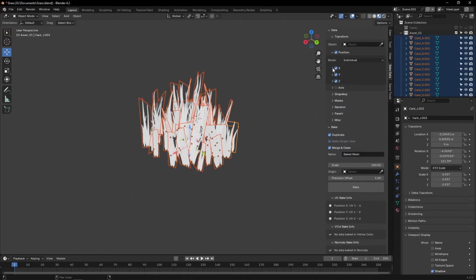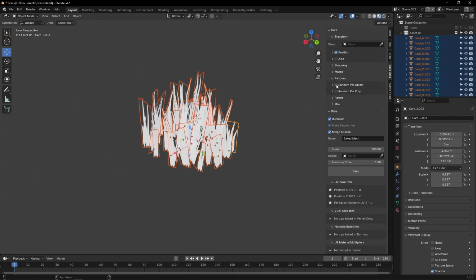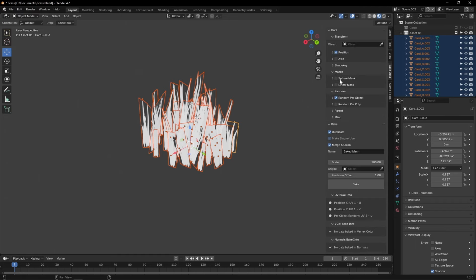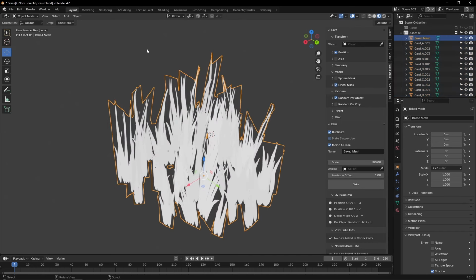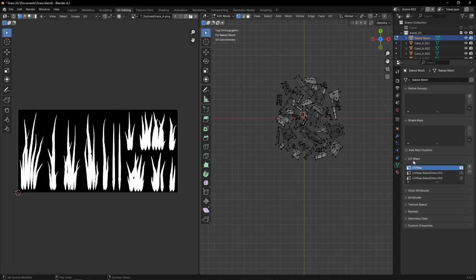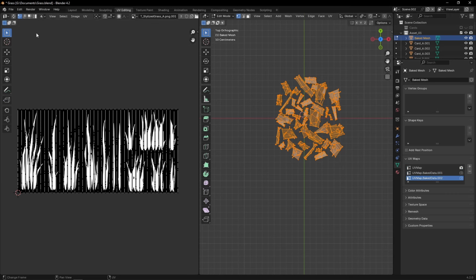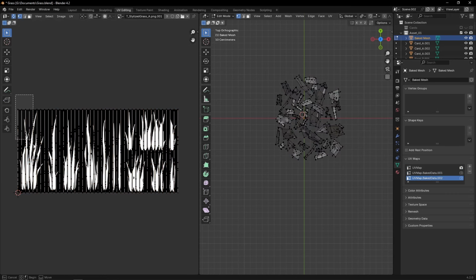And the reason I've kept LOD 0, 1 and 2 part of the same object is that I really like to bake a random value per card in UVs. It's extremely useful for lots of shader tricks, like say to offset the wind animation per card, or add a bit of tint variation to the albedo per card and so on. And the way my add-on works, well, this random value is generated and baked per object.